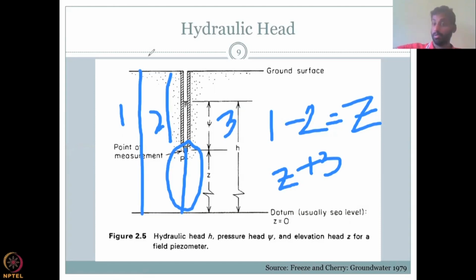You do this to another well. So I walk to another groundwater well and I do another H. I know the distance between the wells, and then I would do the equation as Q is equal to minus hydraulic conductivity. Since I am in the field, I would ask what type of soil it is, and then I know the hydraulic conductivity from the values I showed from the Freeze and Cherry book.